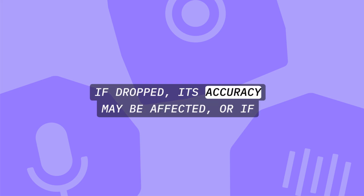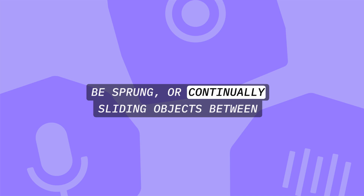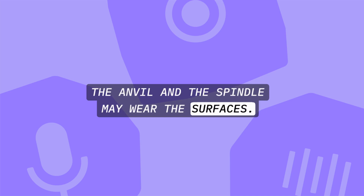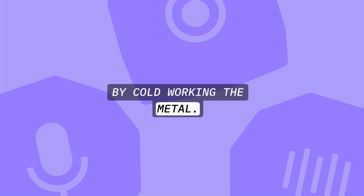If dropped, its accuracy may be affected, or if the spindle is over-tightened, the frame may be sprung, or continually sliding objects between the anvil and the spindle may wear the surfaces. How do you work harden a piece of metal? By cold working the metal.